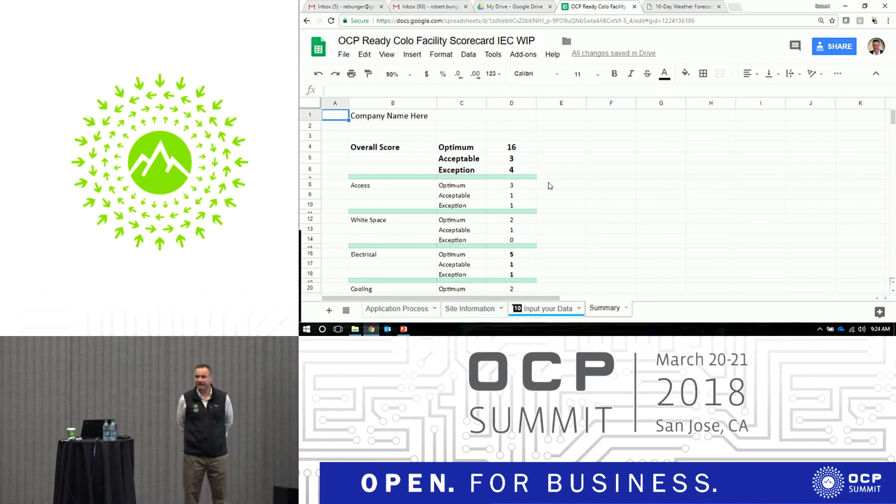A lot more detailed information about the electricals, like ITHD, ramp up on generators. There's usually a control ramp. OCP specs these things. I don't see that in any of your list of items. Oh, you mean from the rack and power V2 rack? Yeah. That's a good question. Okay, so that's good input. So you're saying double check the V2 rack specs and pull that in for ITIC curves, ITHD.